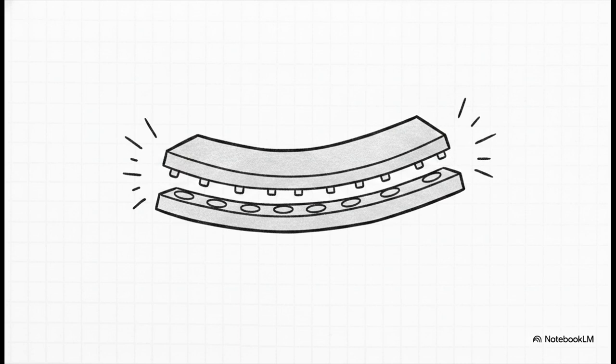Because the layers expand and contract at different rates during temperature swings, modern, ultra-thin substrates literally flex and bow. This violent warping lifts the corner connections right off their pads, completely ripping them apart into what engineers call non-wet opens or head and pillow defects.